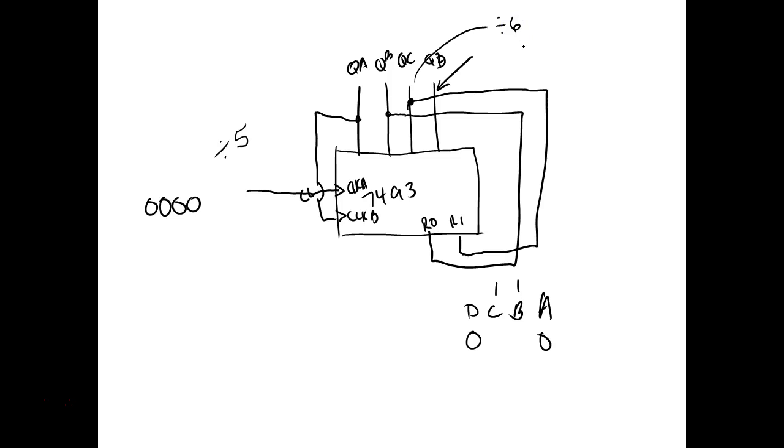And what's nice about the 7493 is it's got the NAND gate in there, right? You understand? And you can usually set the modulus without adding anything else to it. Because I can monitor 2 inputs. If I wanted to monitor 3 inputs, then I could just use another AND gate. So we can set this thing up for almost any modulus we want.